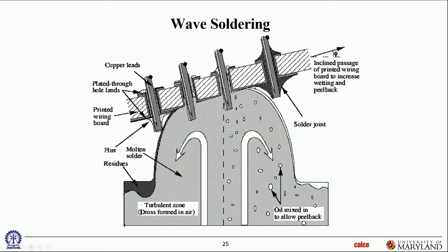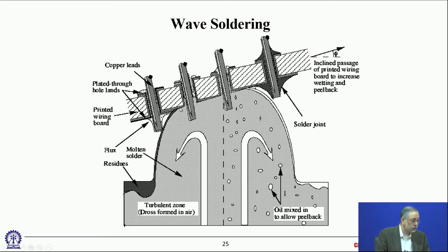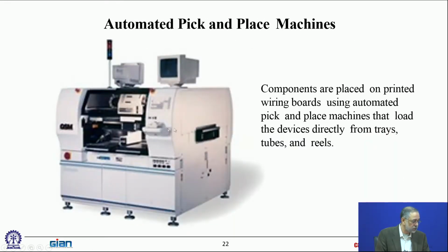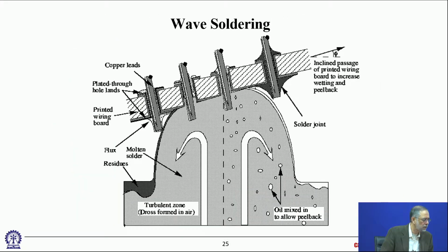Okay. And finally, just one slide. I'm not going to talk a lot about it. This is wave soldering. For through-hole components this is how we do it; for surface mount components, we stencil print, we pick and place, then we go through the reflow oven. I'll talk about the reflow oven in a minute. That should have been here. Where did it go? Oh yeah, reflow is coming next. But in fact, we'll come back to the wave soldering later on.